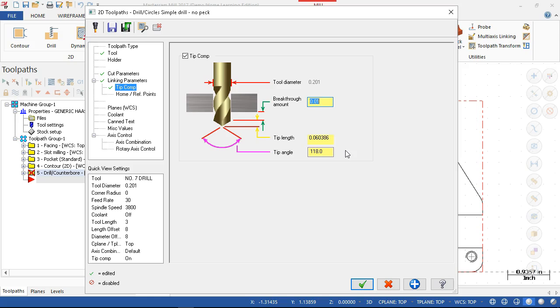All right, so are we going to get out the cordless drill and the tap, and while the next part is running, chase all those threads, or are we going to drill it deep enough that it can pick up the next hole? Or is our fixture custom enough that I can drill an oversized hole so that it has relief on the backside, that when that spiral point tap is pushing the chip ahead and I'm concerned about pack up, it has room to pack up.